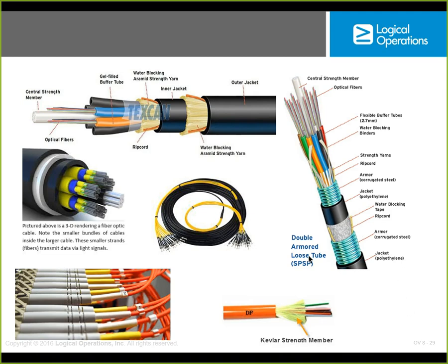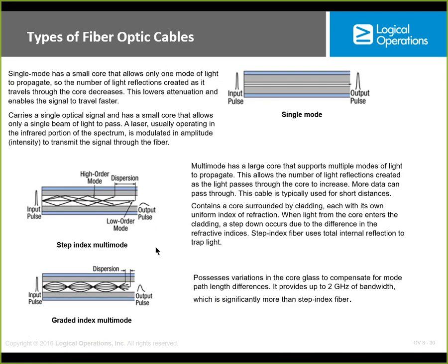The one over here, the armored fiber, there was a fiber manufacturing company in Roanoke that lost all their internet connection because a rat chewed through their fiber. And they like this stuff. So if you're in a situation like that outside with squirrels or whatever else, you need to use the armored fiber in order to do that. Different types, and you can have here bundles. If we were going into a room, we would want to take a bundle in, and then we would run the different fibers to the different locations in the room itself.